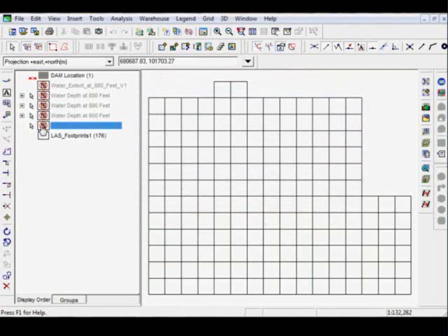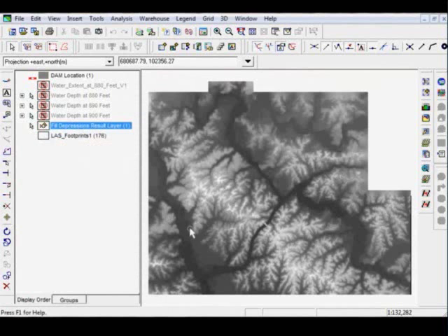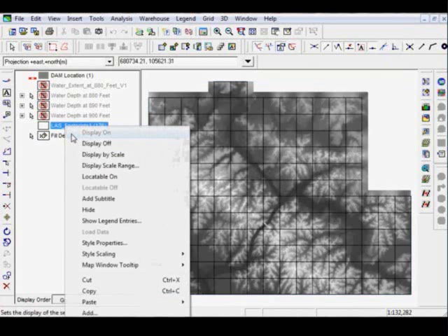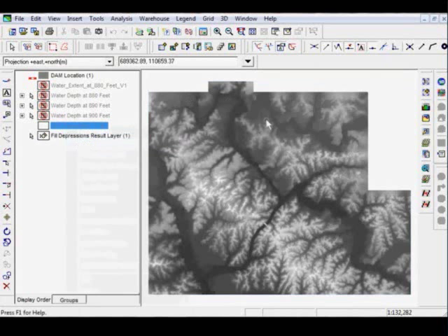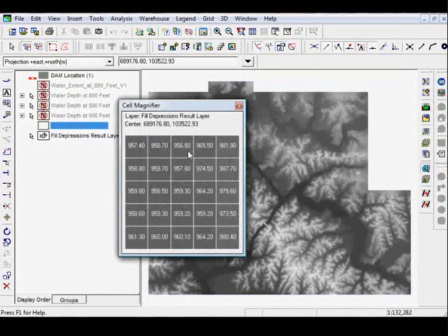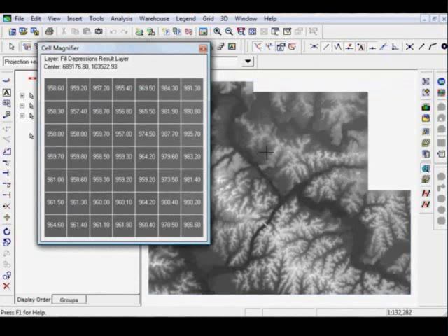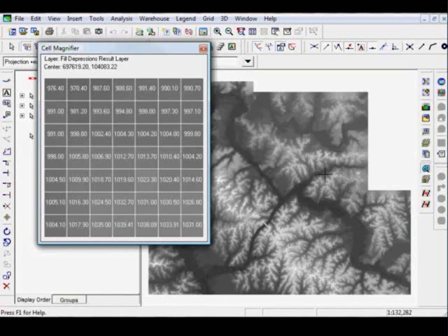So what we did is we used the LiDAR workbench to create a digital elevation model here. And of course, you can pop up the footprints just to see how those are matching up. We don't really need that, but I did want to show you that that's where they came from. And of course, I've shown you a little bit before how we can quickly query and get elevation data for that, just so you get an idea of what the elevation in the area is. We can poke around and we can do profiles, a whole bunch of things, but really just wanted to show you that.